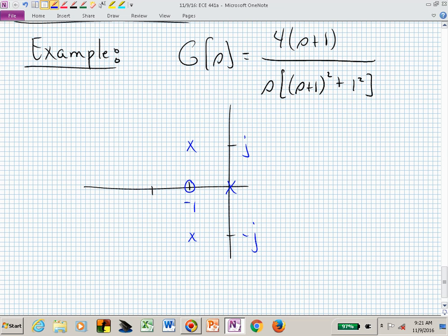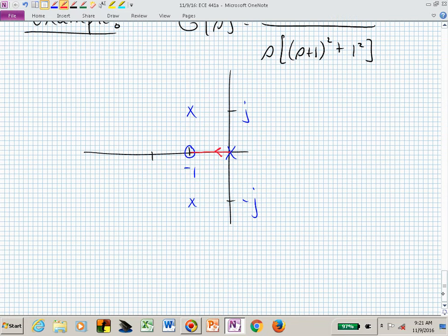We've already done rule number 1 by just putting down the poles and zeros. Which segment of the real line belongs on the root locus? Is there any part of the real line that is on the root locus? That pole is going to migrate towards the 0 at -1. What's the pole 0 excess? We have 3 poles, 1 0. Our pole 0 excess is 2.